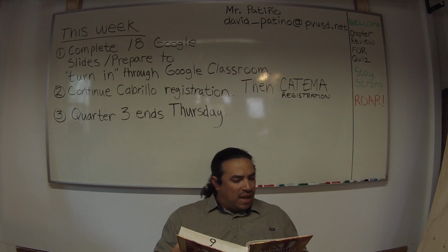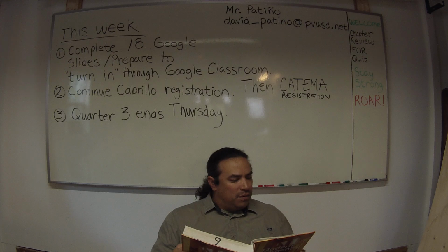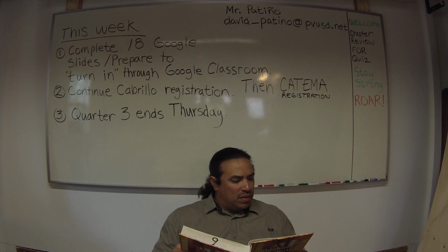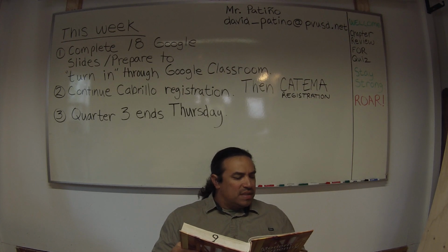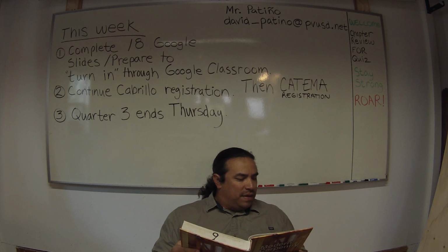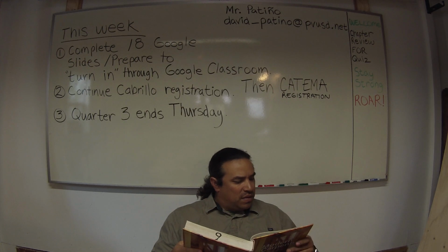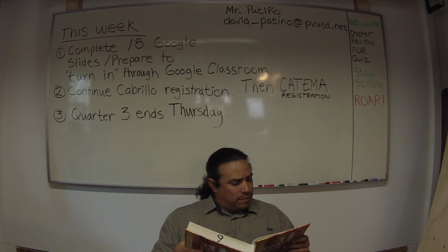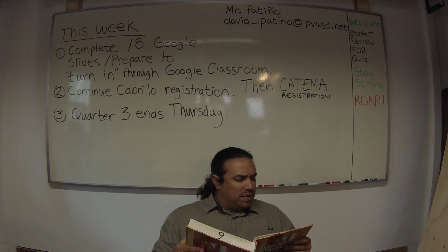Lumber can be cut so that annual rings form an angle of more than 45 degrees with the surface of the board. This method produces lumber called edge-grained if it is softwood, and quarter sawed if it is hardwood. It is more difficult and expensive to use this method. However, it produces lumber that swells and shrinks less across the width and is not as likely to warp.